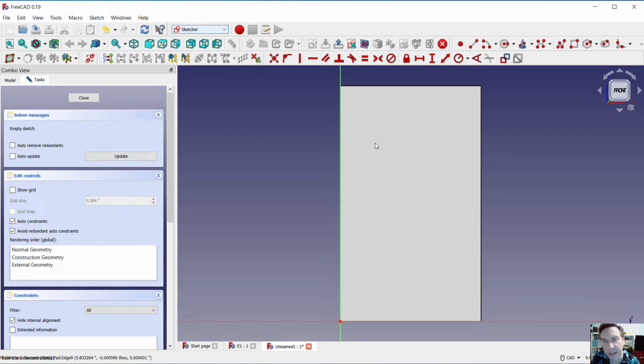Okay, now that we're here, we're going to put in a rectangle. So we're going to go back to the rectangle tool. But before we do that, we have to make some points for it to be able to lock into. For that, hit this little arrow if you don't see this, and what we're looking for is this tool. Look carefully, it might be hiding somewhere up on the screen. It creates an edge linked to another edge. So select this edge, and select this edge right here.